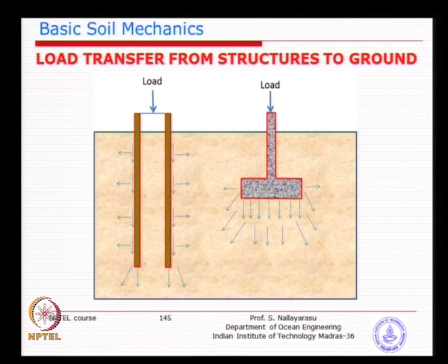So you see this particular case, predominantly the footing type of foundation, the soil is getting vertical pressure just immediately beneath the foundation, but then it distributes in a manner depending on the type of soil. If it is a sandy soil, it takes a certain path. If it is a clay type of soil, it takes a different load distribution, or if it is a rocky material, directly it is taken by bearing.